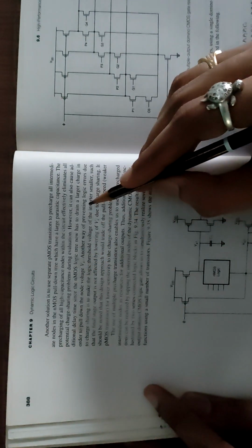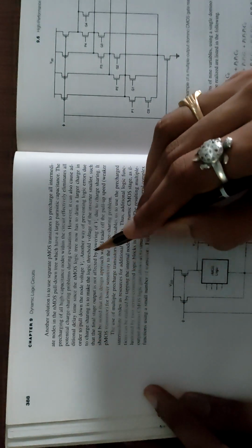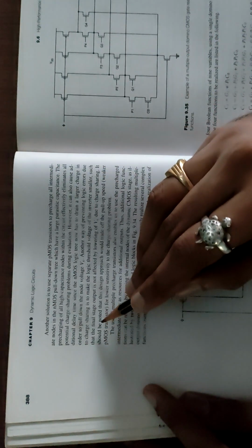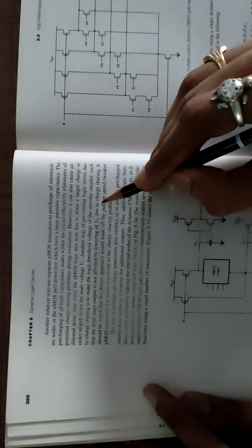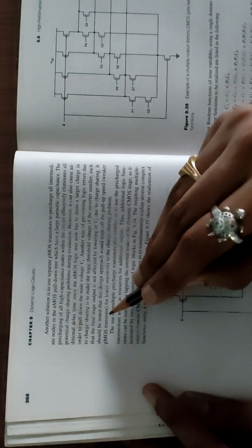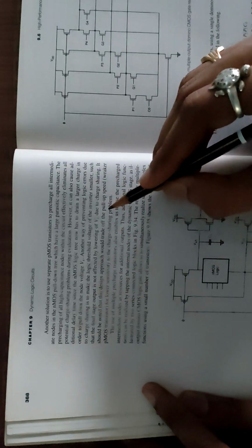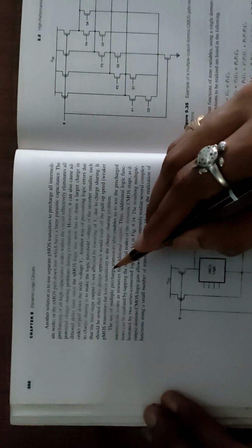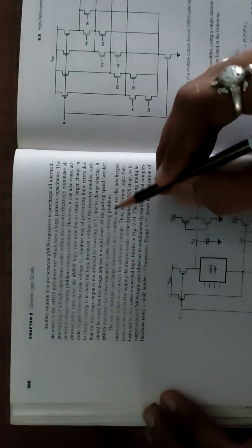Another way of preventing logic errors due to charge sharing is to make the logic threshold voltage of the inverter smaller, such that the final stage output is not affected by lowering of Vx due to charge sharing. It should be noted that this design approach would trade off the pull-up speed, with a weaker PMOS transistor, for lower sensitivity to the charge sharing problem.